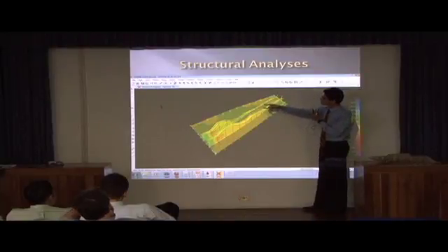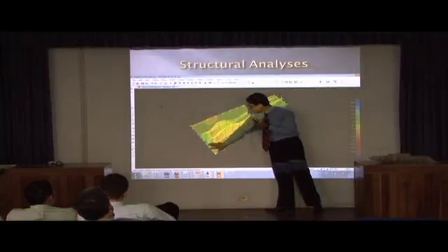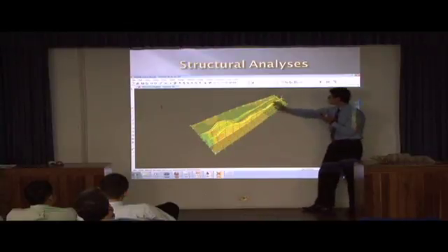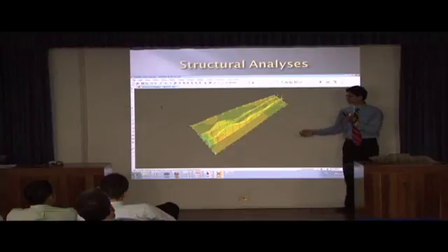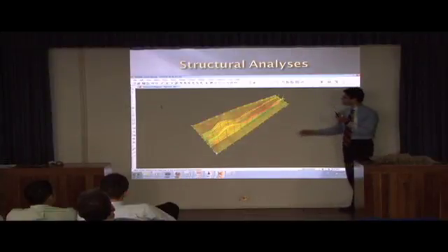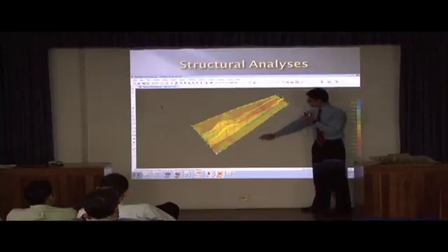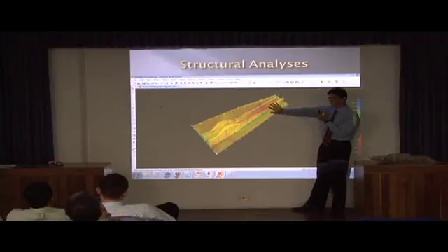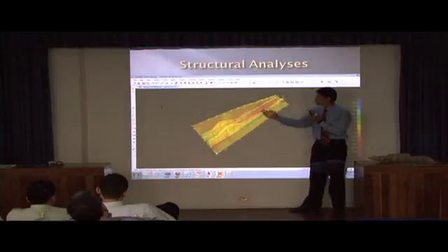We have now the transverse shear stresses. We can check that a high concentration of shear stresses is here and here, but here we have the most important one. That's why we reinforce this section with the brackets. And these are the transverse stresses. We have the highest reflected in this flange of foundation number 1 and on this part, but these are the more critical.